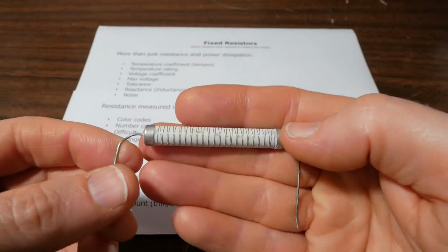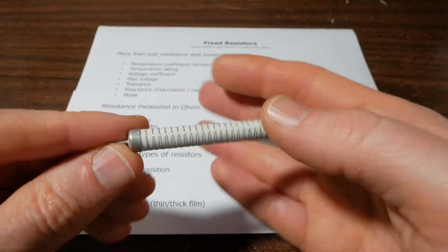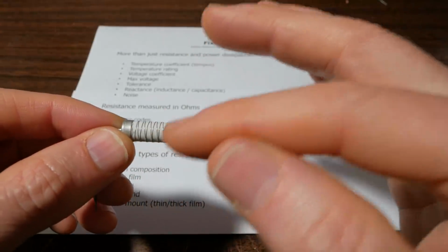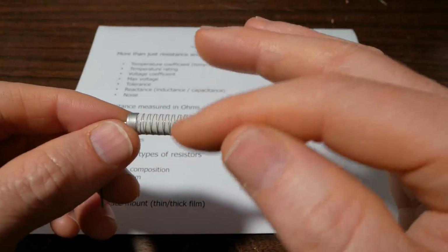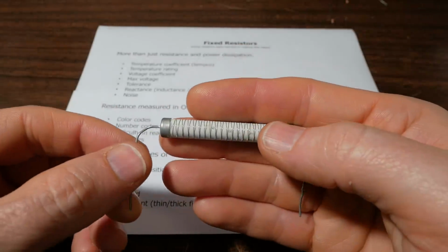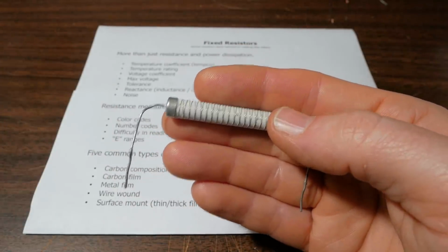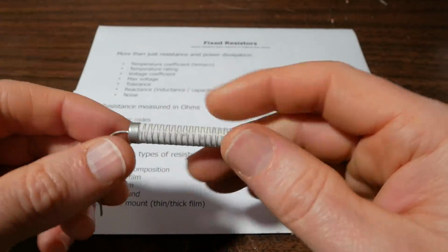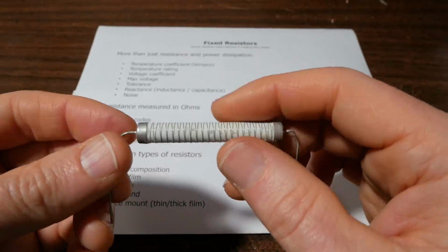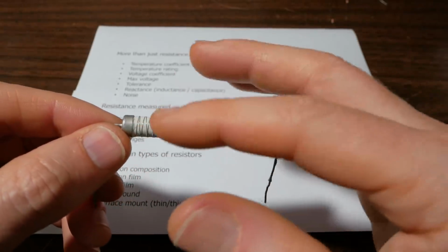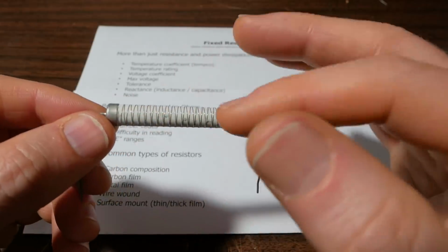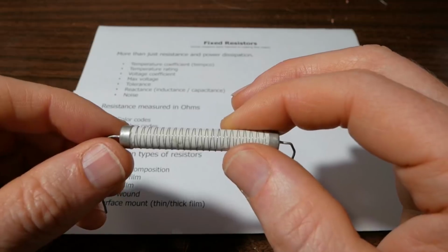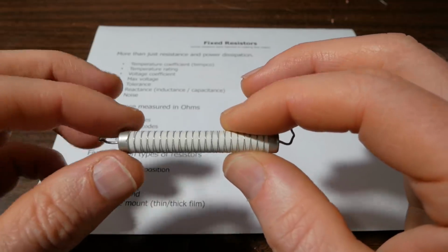Now let me show you one type of wire-wound resistor that's low inductance. If you notice here, there's one coil that's going clockwise and another one spiraling counterclockwise. This is called the Ayrton-Perry type winding. And I hope I'm pronouncing that correct, because it's somebody's name, you never know if it's right or not. But what happens is, when you have a coil going one way and another one going the opposite way, you're canceling out any inductive effects because the electric current is passing in opposing directions.